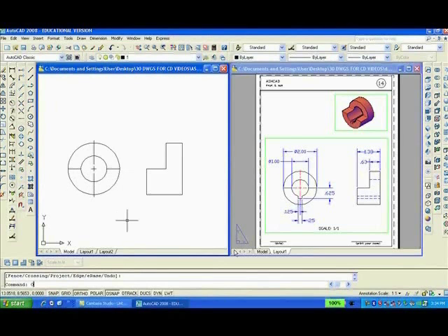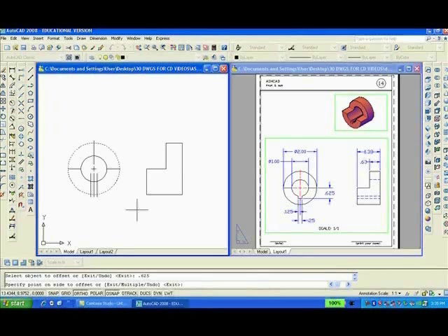Now you want to offset. O enter, 0.125, enter. This line in that direction. Repeat the command, and there. Also, you can offset, enter, 0.625, enter. Offset 0.625, enter. Select this center point here, center mark there, and bring it down here like that. And then zoom in.